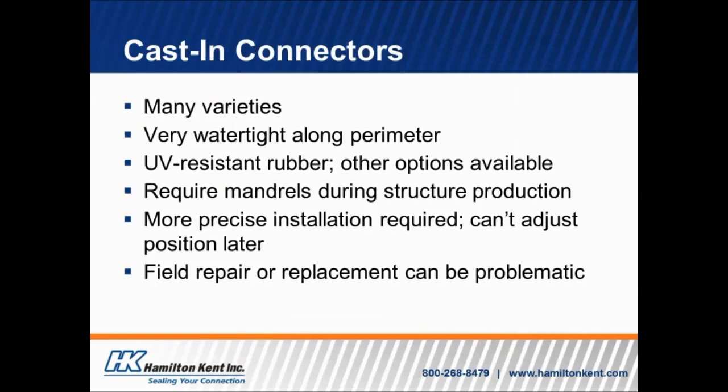Casting connectors. Now let's talk about connectors that are actually cast into the concrete. There are a big variety of connectors, and I think I showed you a few of them in an earlier picture. They're very watertight along the perimeter, and unlike a mechanical connector, where you're relying on making sure that it's tight on the inside diameter of that hole in the concrete, with a casting connector you don't have to worry about that because the connector is inside the concrete.